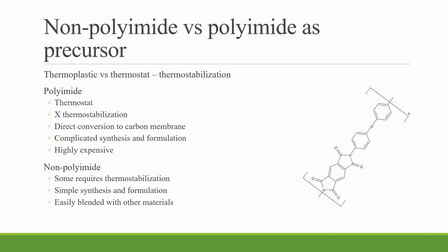And non-polyimides, such as polyphenylene oxide or polyetherimide, are cheaper, but they require an extra step in the conversion into the carbon membrane, which is thermostabilization.